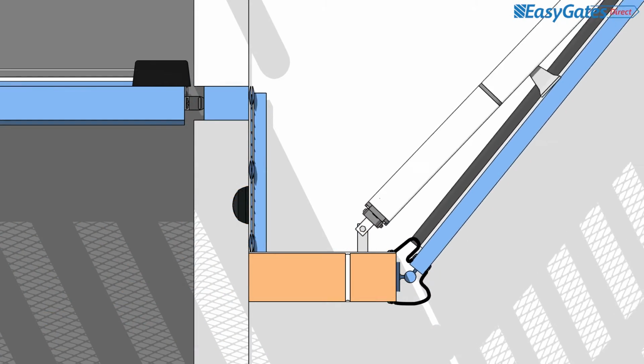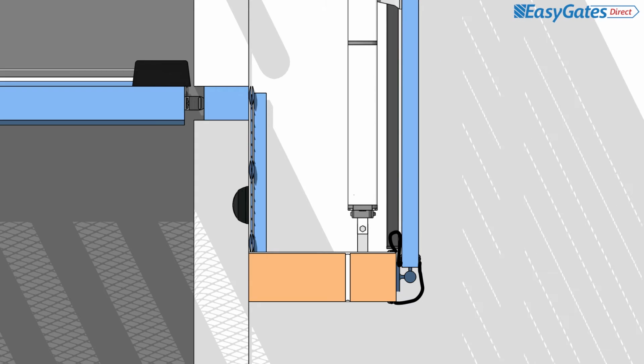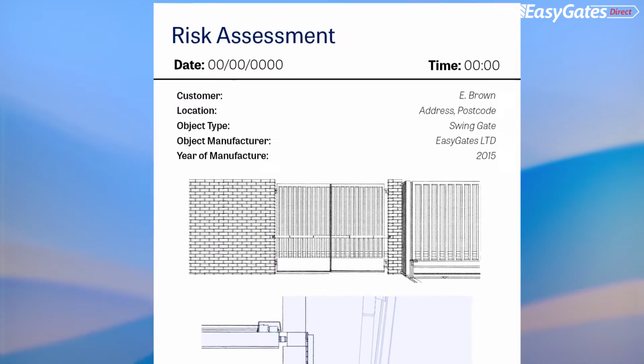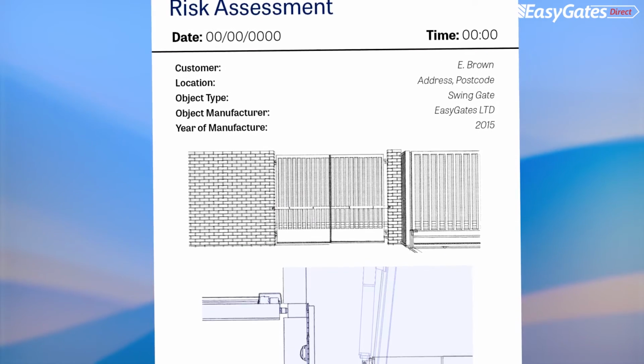When using hinge guards that are designed to prevent access to the pivot area of the leaf, they must be durable, resistant, and designed in such a way that they do not cause a hazard to still exist. Please note, all safety solutions including safety edges should be assessed in the same way and address all potential crushing and shearing hazards. When retrofitting these solutions to existing gates, remember to create reports or documents presenting the values recorded.